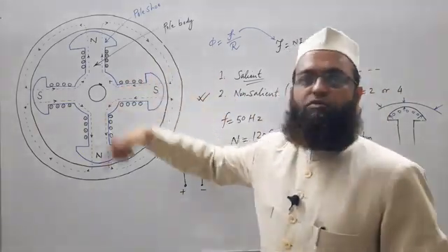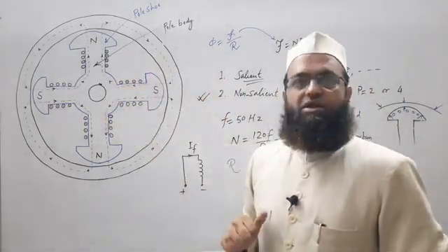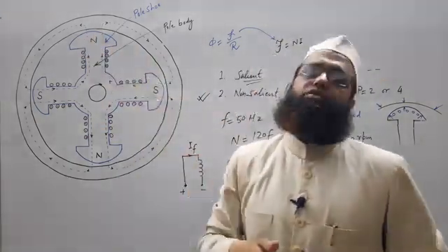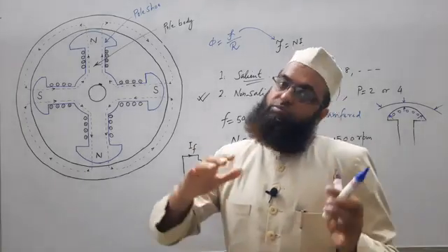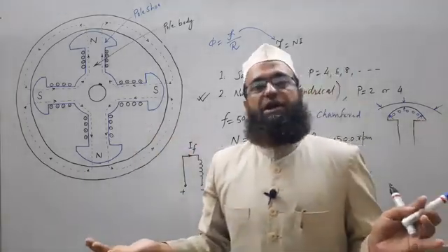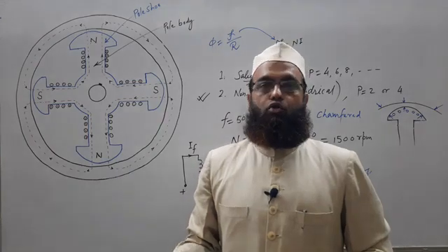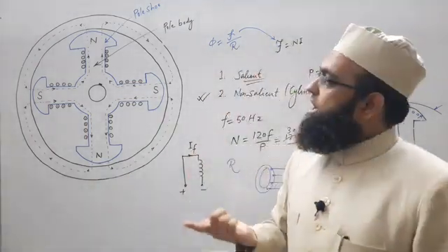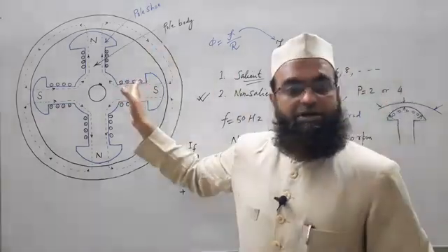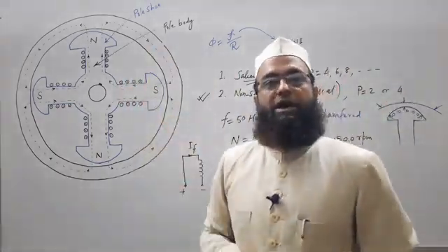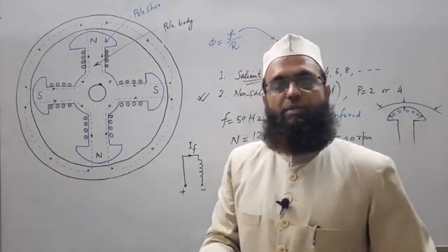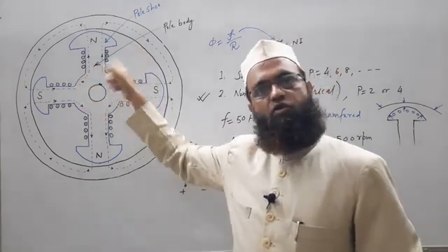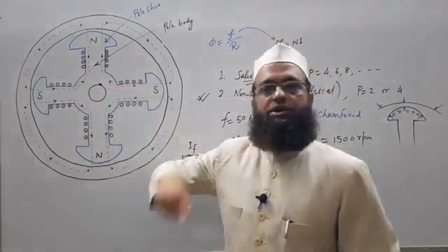So a rotating magnetic field is produced, and the rotor is stationary. So copper bars are there in which EMF will be induced, and these bars are shorted, which means the circuit is complete, so corresponding current will flow. Those current carrying conductors will experience force because the rotating magnetic field is there. Again, as per Faraday's law of electromagnetic induction, relative motion will be observed by the conductors on the rotor. So EMF is induced, current is there, force is there, and it will start rotating.